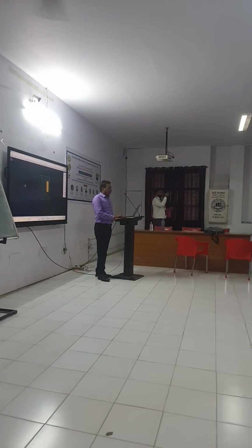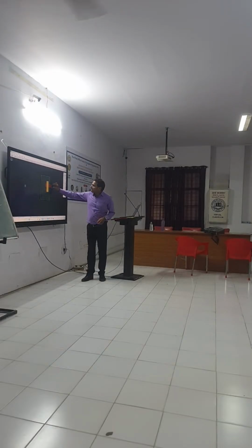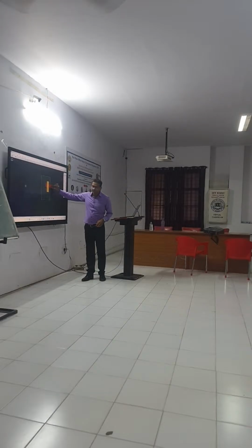Then cross it with polysilicon. So this is the polysilicon. This polysilicon width is the channel length. You know the layout design rule. So this is the polysilicon width, that is the channel length. And the width of the P diffusion is the width of the MOSFET. The drain can be on this side or that side, it is symmetric, so you can take either side.